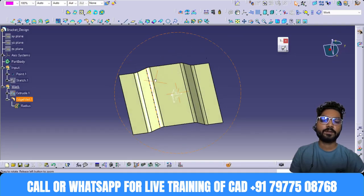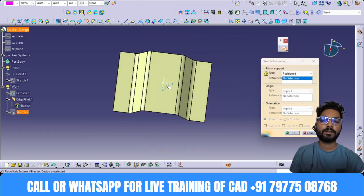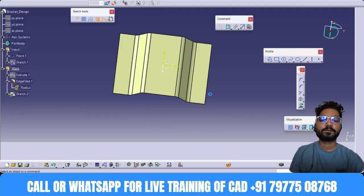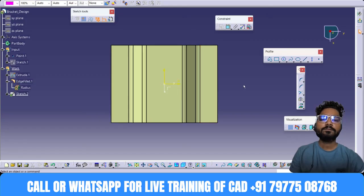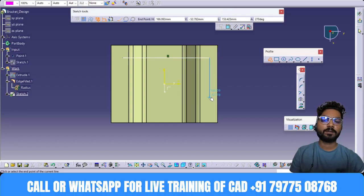Now I'll create one sketch again on the XY plane. The projection point is this one, and set this V and H correctly. Swap, click OK. After creating this, we'll create one rough shape for the shape of the bracket.